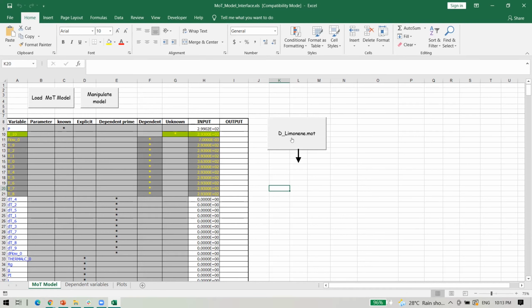So a short path evaporator is one way to remove very small amounts of material without destabilizing the compounds. That was what was shown. Here, it is just a binary mixture of limonene and water. Water will vaporize out and limonene will concentrate.